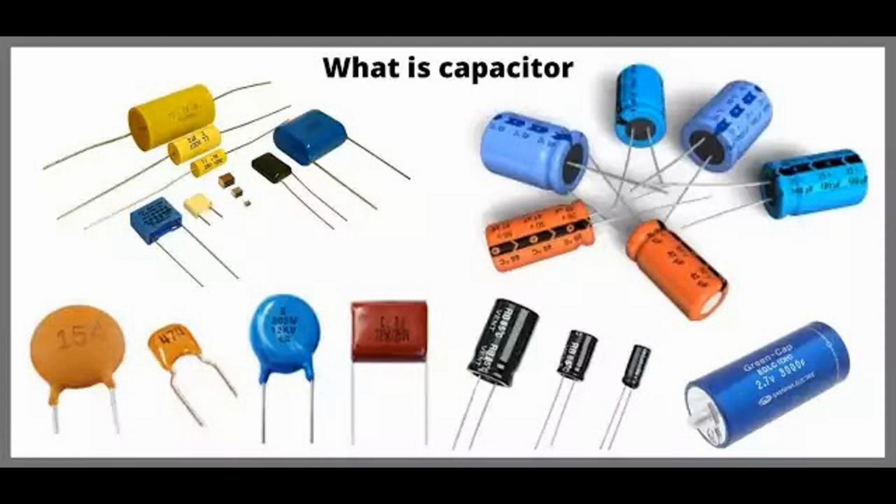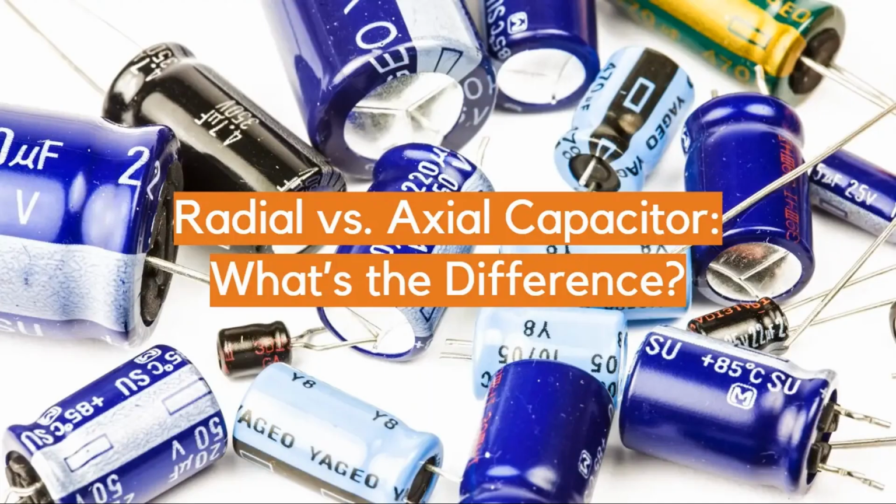Aluminum electrolytic capacitors. The capacitance of aluminum electrolytic capacitors can be affected by temperature variations and operating voltage. Their capacitance may decrease with increasing temperature and voltage. In addition, aluminum capacitors may experience a gradual decrease in capacitance over time due to aging and the gradual breakdown of the dielectric oxide layer.